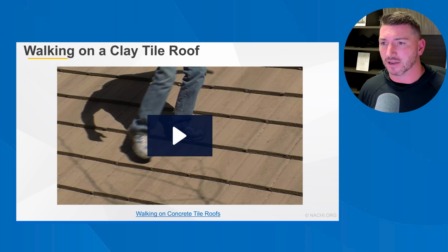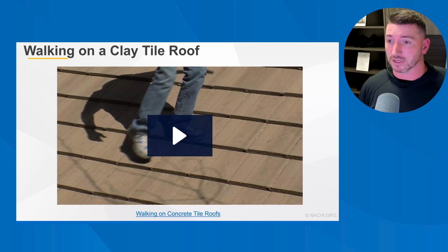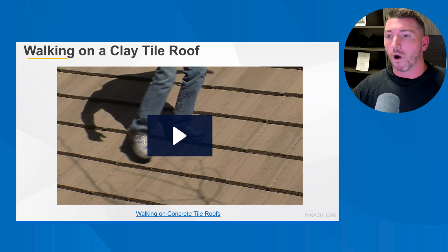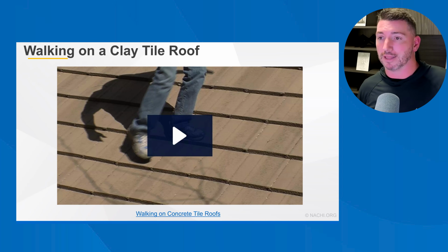The thickness of a cedar shake roof is a huge thing to take into consideration if you're considering walking on a cedar shake roof. You'd not want to walk on a shingle. You could walk on a shake, but the principle applies there as well. Walking on the headlaps is going to avoid breaking that material.